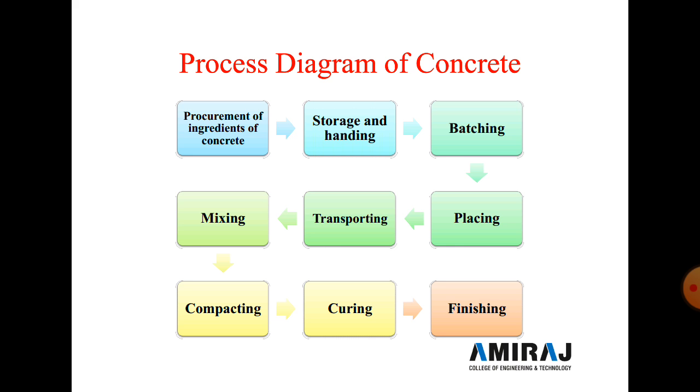Now next is storage and handling. Where do we store the material? Cement is stored in a cool and dry place. Why do we store cement in a cool and dry place? Because if the cement comes in contact with water, it hardens in a short time. Sand and aggregate are both stored in an open area or near the site.